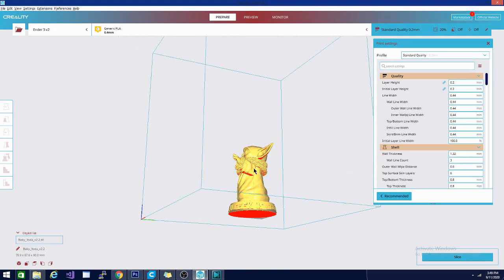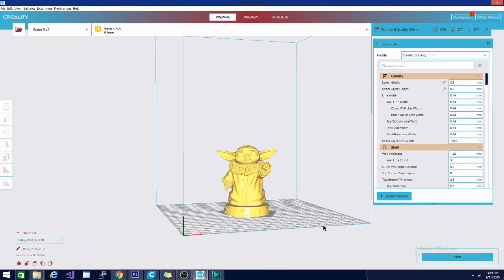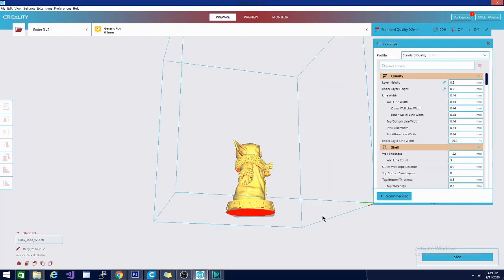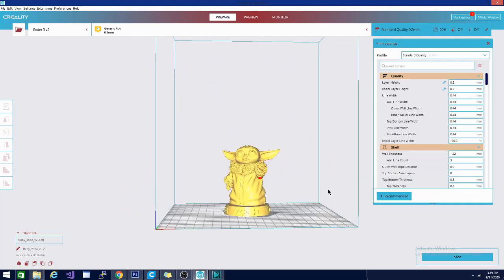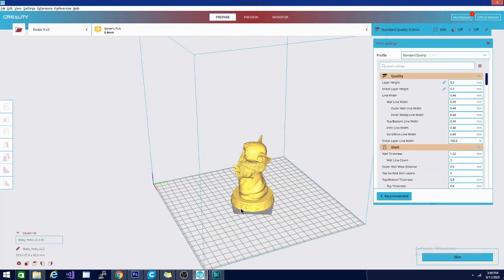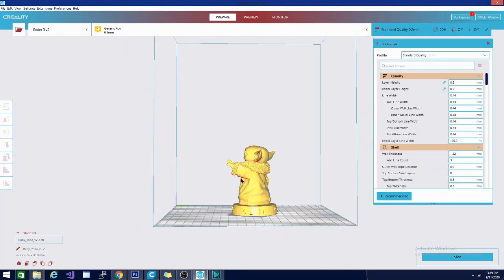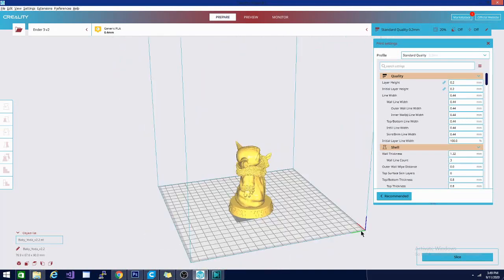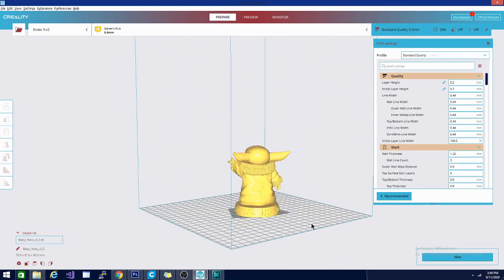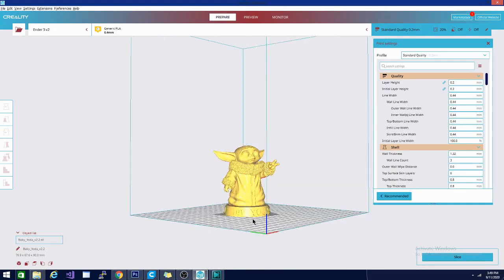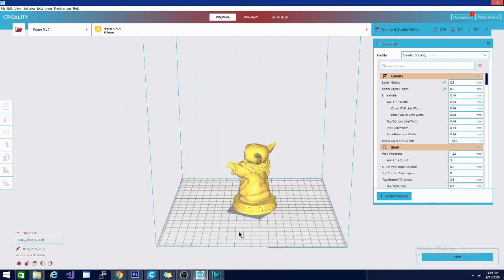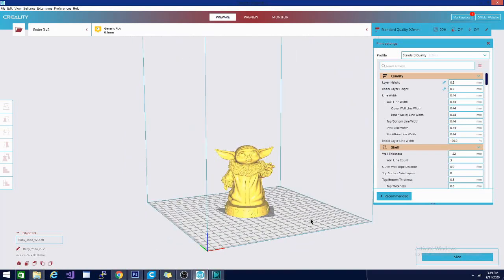When you're looking at the slicer here, these red areas are places known as overhangs, and those overhangs are places that are going to need what's called support. And support is basically extra plastic. It's going to build up underneath your model so that when it gets to this point right here, it's not trying to print an arm in thin air. It's got a little bit of plastic underneath it to build on. The support's pretty much easily removable with different options for how it interfaces with the model to leave less of a mark or do different things, basically.